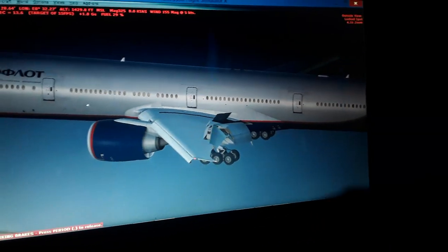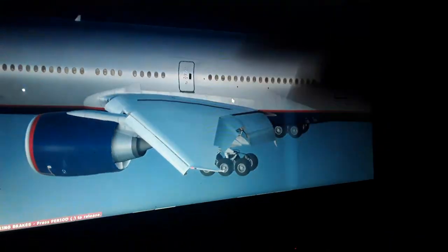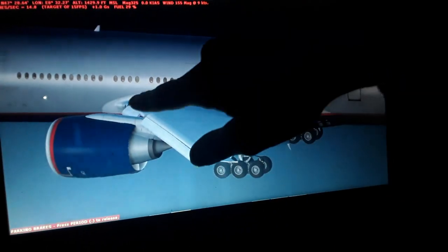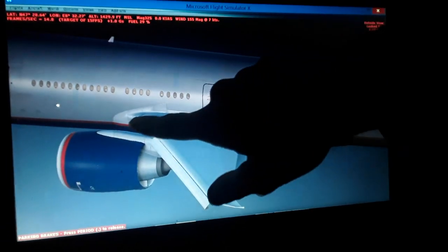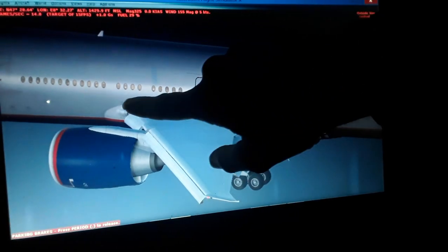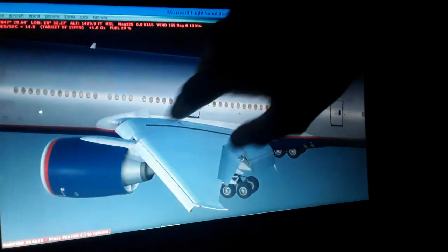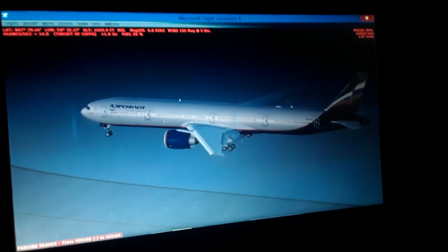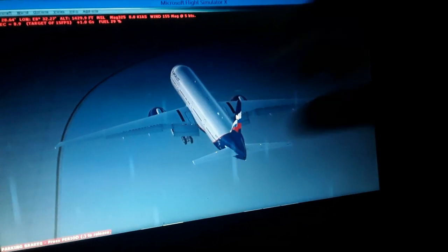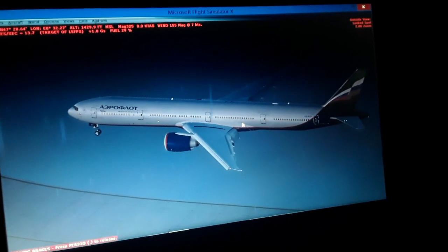So we have differential pressure. You can see the top surface of the wings is more curved. It has higher curvature. So using the Bernoulli theory of fluid again, for below and for above, you can see the airflow of the air mass is moving much faster above the wings, so we have lower air pressure, negative air pressure above the wings, which sucks the aircraft weight and wings up into the air. So we have positive higher air pressure below the wing and negative above the wing. So these are all the theories we need for